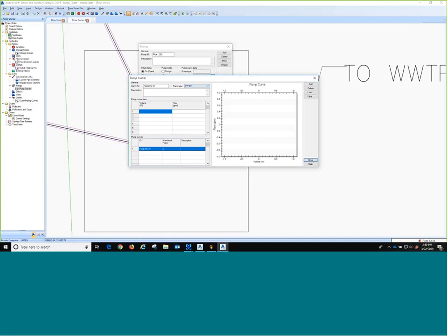Now you can look up in the help file what each type of pump is, but basically this is a volume flow inline pump. Here's a volume flow, or a depth flow inline pump. So I'm basically setting up logic for whenever the depth reaches a certain level in my pump. I'll tell it when my pump's going to turn on and what my flow is at that point.